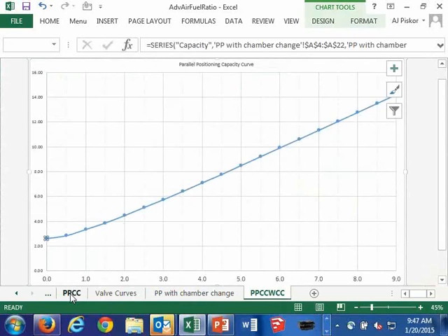Because I have an extra inch of suction in my chamber, it's going to be pulling additional airflow and fuel flow through the burner, so everything's going to jump up. But the good news is that with this particular burner, the air and the fuel differential pressure requirements are pretty close, so it'll affect each the air and the fuel equally.